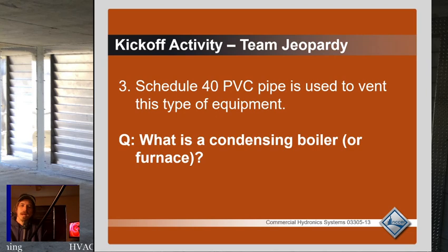They don't want to be liable for any issues caused from PVC pipe being used for venting a gas appliance. So that's where a lot of that plastic, like polypropylene gasketed piping comes from, is the fact that they'll actually say their piping is good to be used as a flue vent, whereas the PVC pipe manufacturers will not. If you read their manuals, it is not to be used for that. So it's just something to keep in mind.